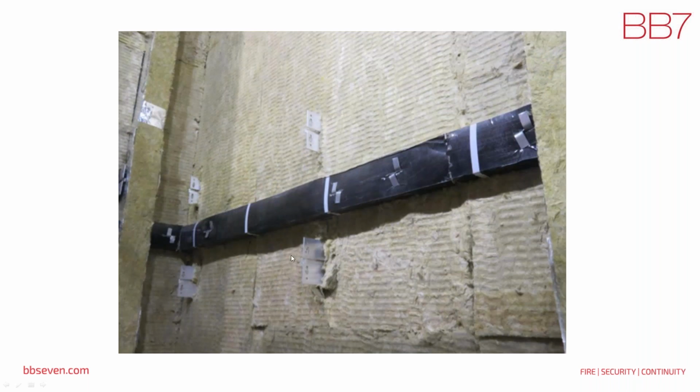Again, we've got a close-up of what the intumescent and the fixing looks like for the fire barrier. Remember, these protect compartment floors, and so it's this black material here that will char up, known as intumescent, and it will then abut onto the inside of the front surface. In other words, your rain screen panel.